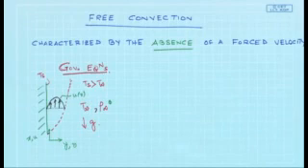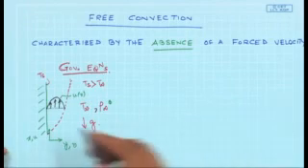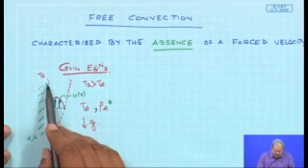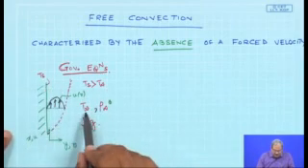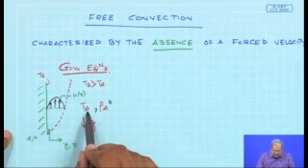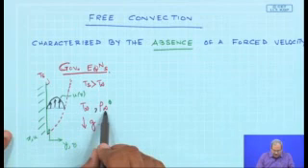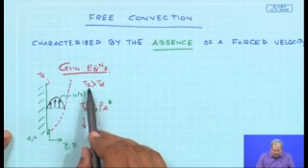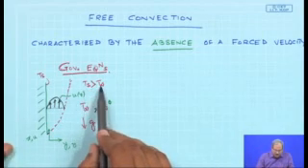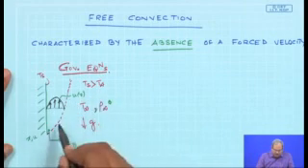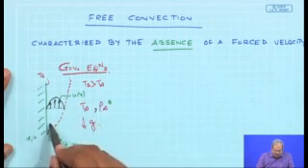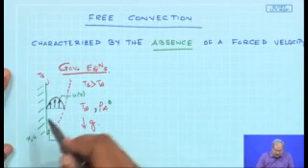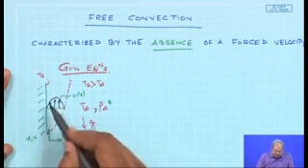So let's look at the figure over here, which shows that I have a plate which is in contact with air. The plate temperature is Ts and the temperature of the surrounding air at a point far from the plate is T infinity, and the corresponding density of air is rho infinity. The gravity is acting this way, and we will assume that the temperature of the plate is more than the temperature of the air. So therefore the fluid near the wall, its temperature will increase, its density will decrease, and it will start to rise up.